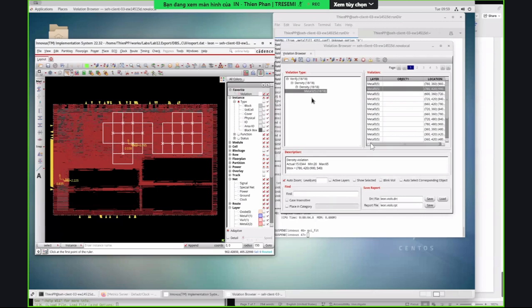The third party tool actually uses the rule deck to check all these DRC violations. So if we use Innovus to do metal fill, it doesn't see all the rules, so you may be clean in Innovus, but then when you go to the signoff tool like third party Calibre, you have a lot more violations. That's why we don't use Innovus. It basically doesn't have a complete set of rules. Okay, that's all I have, Tim.